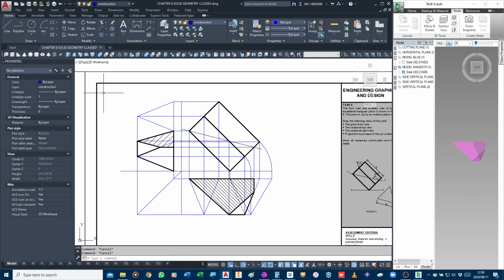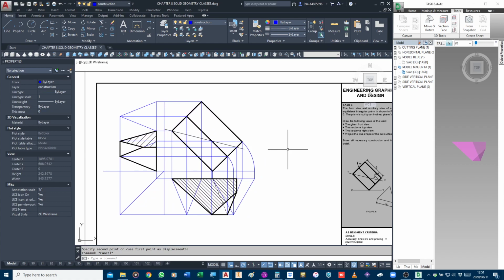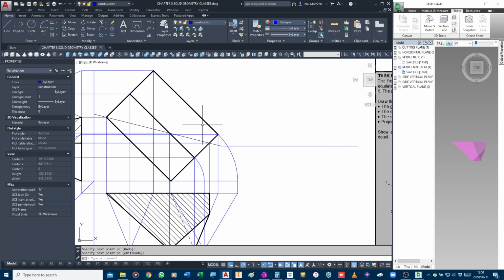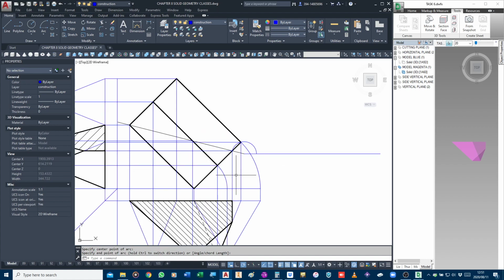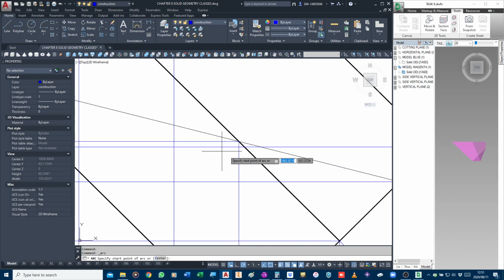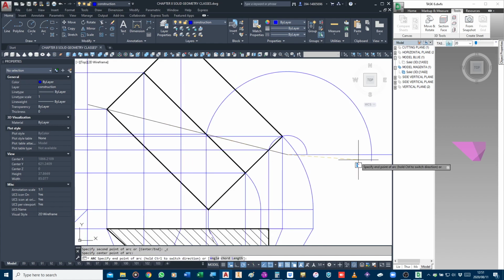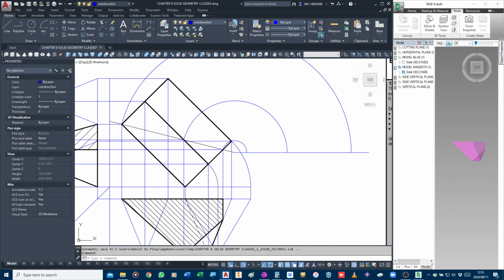And if you think back to what we said earlier, it is pretty easy to do the true shape from here. Wherever your cutting plane stops, we can draw a horizontal line. From there, we are going to use our compass. From there to there, that will be my one point that we're looking for. The next one is from there to there and to there. And the last one would be from here to here to here.